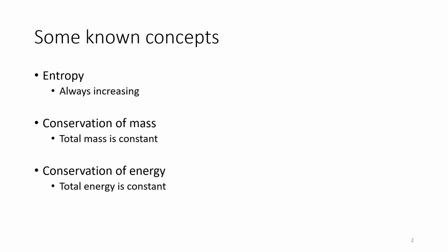Yes, damping. When you were taught vibration, you were taught that there are three components to a vibrating system: the stiffness, the damping, and the inertia. The damping is the non-recoverable side. Once whatever energy goes in, it can never be recovered.